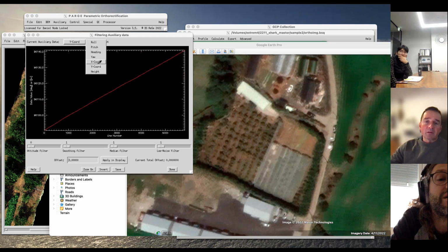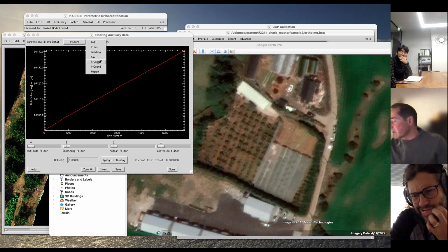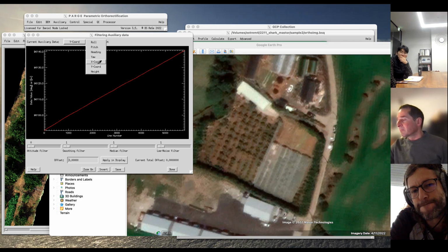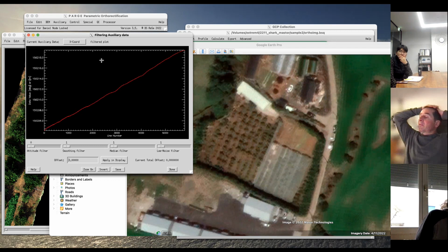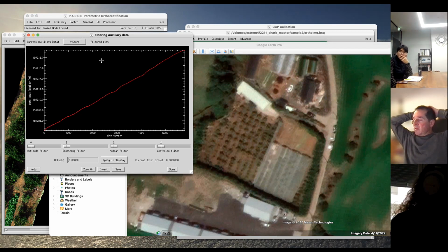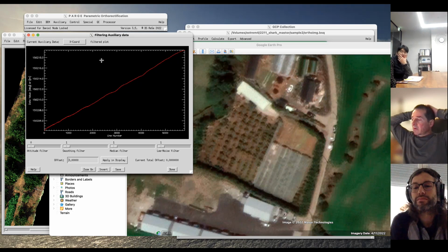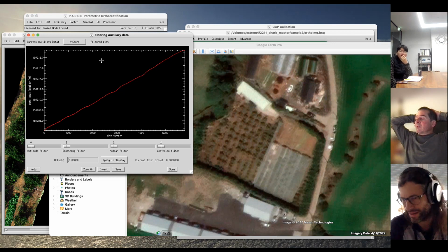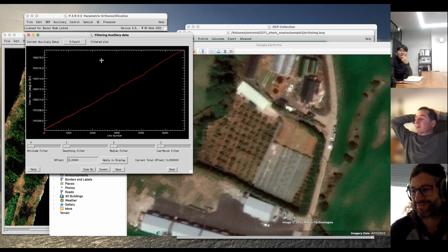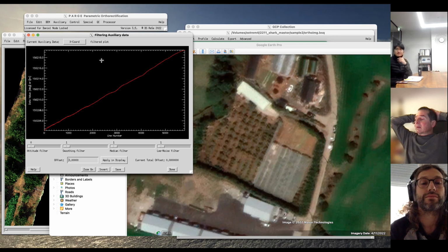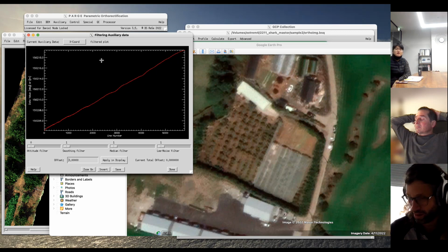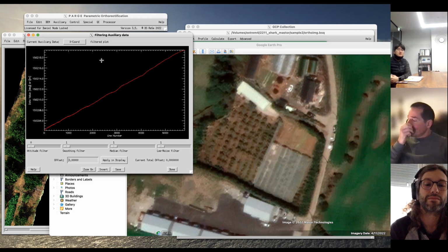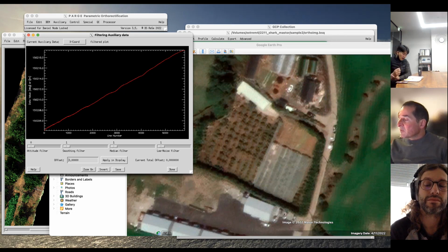If the auto photo is really correct, then the only reason could be that there is a drift in the GPS, so the GPS is not working. Do you have an alternative GPS? Is this the GPS of the drone or the GPS of the sensor? GPS from the sensor. Do you have GPS data from the DJI drone as well? Yeah, but we do not use the drone GPS data. We only use the GPS from the sensor.